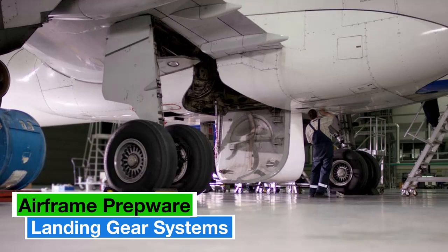A pilot reports that the brake pedals have excessive travel. A probable cause is lack of fluid in the brake system. Excessive wear in the shoulder area of an aircraft tire is an indication of underinflation.